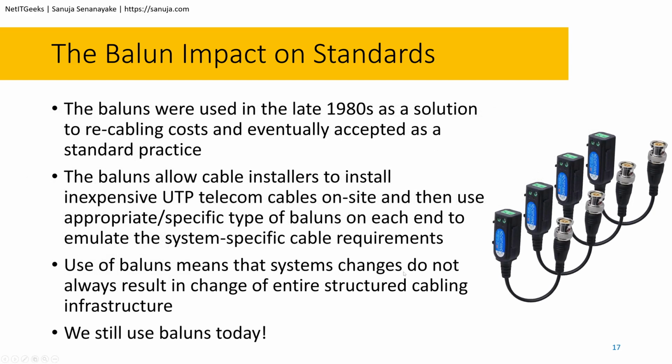The baluns were used in the late 1980s as a solution to recabling cost and eventually accepted as a standard practice. In other words, instead of recabling the whole area with the entire structured cabling pulled out and putting in a brand new one, you can now use these baluns to connect new equipment or different equipment at the end of a currently existing structured cabling infrastructure, because that will convert from one end to another end. The baluns allow cable installers to install inexpensive UTP telecom cables on site and then use